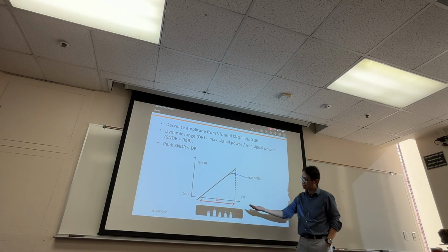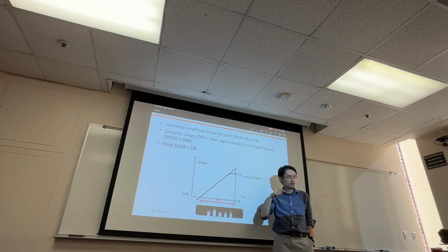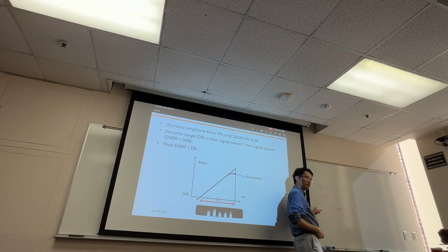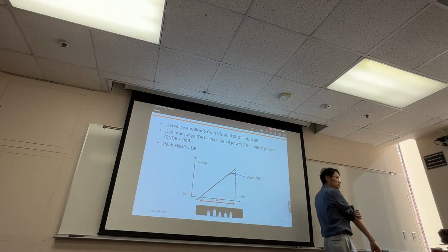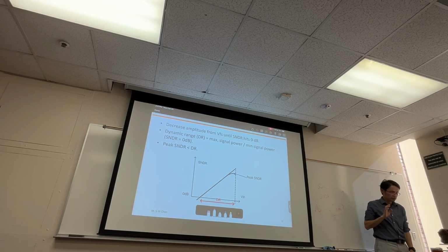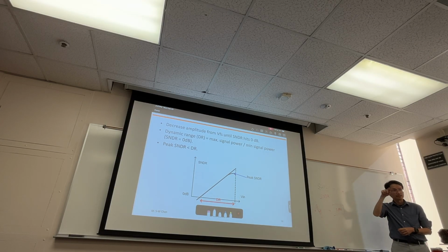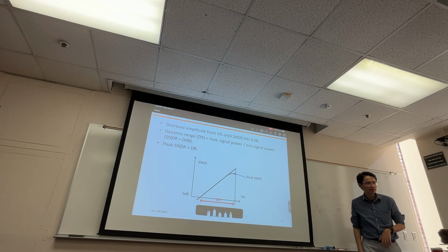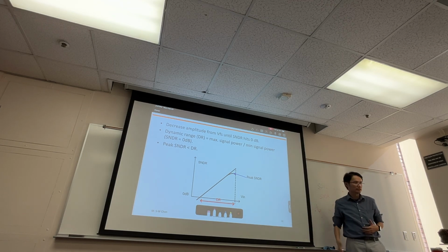What's the slope here if I increase the input amplitude? So let's say I increase the amplitude by 2x. How much do I expect SNDR to improve? How many dB? Oh, by the way, I forgot to mention, you should do it in dB. If you look at the power, it's 10 log base 10 of the SNR ratio, or SQNR or SNDR.